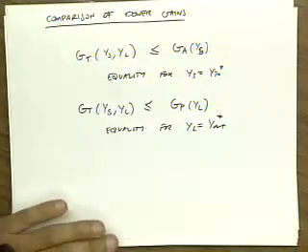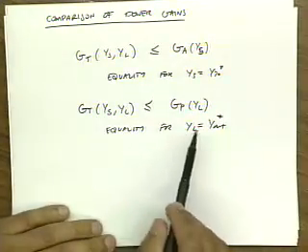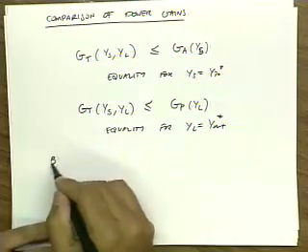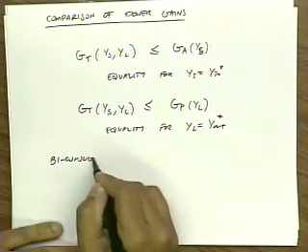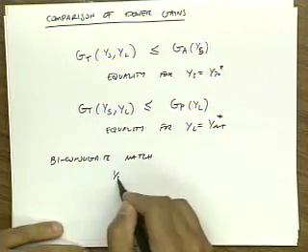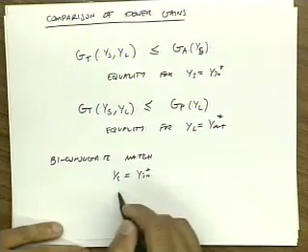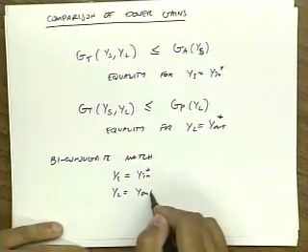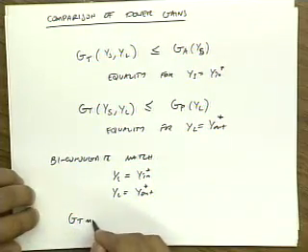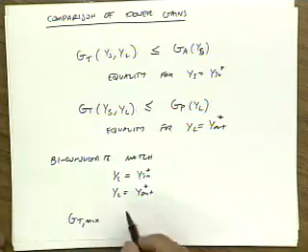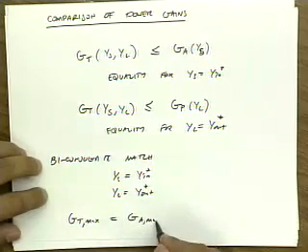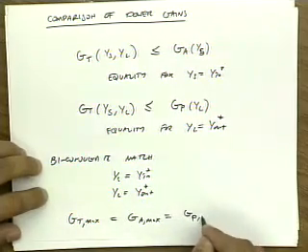So it's now pretty clear that if we simultaneously match the input and output, a biconjugate match, then we have GT max, the maximum obtainable gain as a function of the source and load, equal to GA max, and equal to GP max.